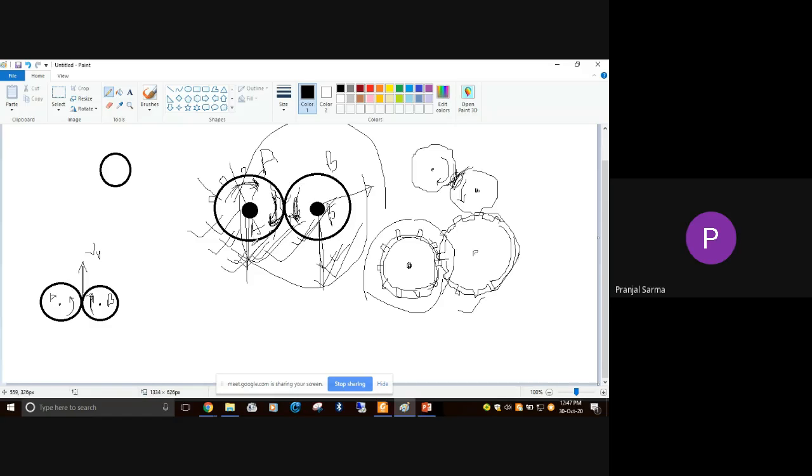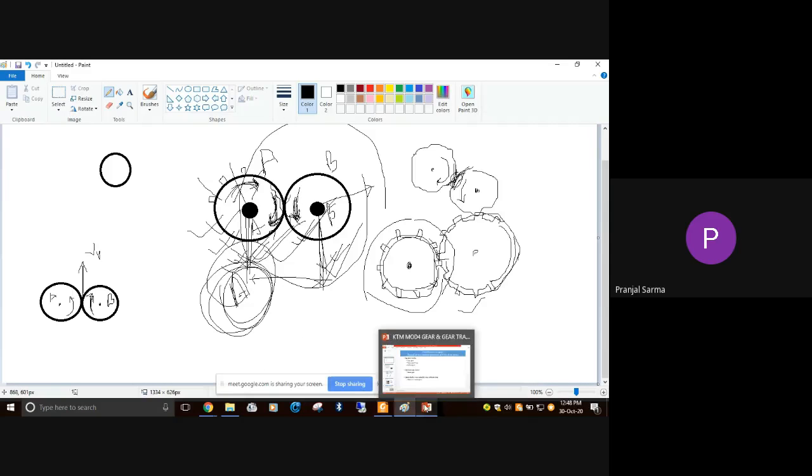Okay, and that's why later on you'll see sometimes, even if we discuss the gears with respect to shaft velocity, you must remember: suppose the driver shaft is rotating with 500 rpm, and we ask what will be the driven shaft velocity, then you must remember that whatever gear has been mounted on the driver shaft is also going to get the same velocity as the driver shaft, because it is keyed to it. It is mounted on this particular shaft. So sometimes it may not be discussed with respect to gear velocity, it may be discussed with respect to shaft velocity, but you must understand that the meaning will be the same.